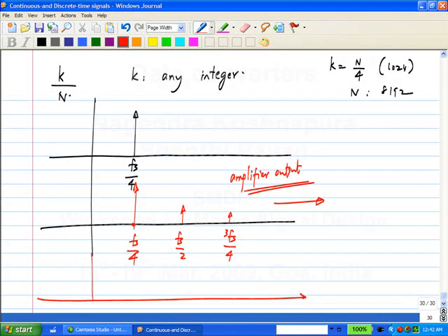You will see the signal peak at Fs by 4. You will see a peak at Fs by 2. What will happen to the 3 Fs by 4? It will alias to Fs by 4. What will happen to the fourth harmonic? It will alias to DC. So you will only get this. Your harmonic has fallen on top of your original signal, so you can't find out the strength of the third harmonic from this. So what do you have to do?